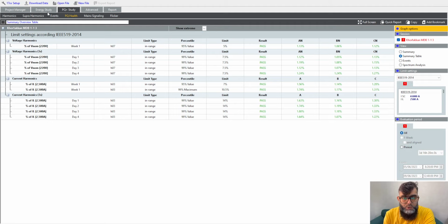Most of our loads are not 3-phase. Most of our loads are single phase. And why do I say that? It's because of the harmonics current flowing in the neutral. Yes, those are balanced, but still, once you see such high values of harmonics in your neutrals, you can reach the conclusion that most of your connected loads are single phase.